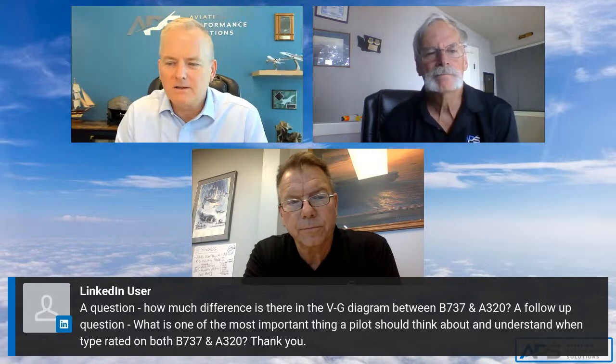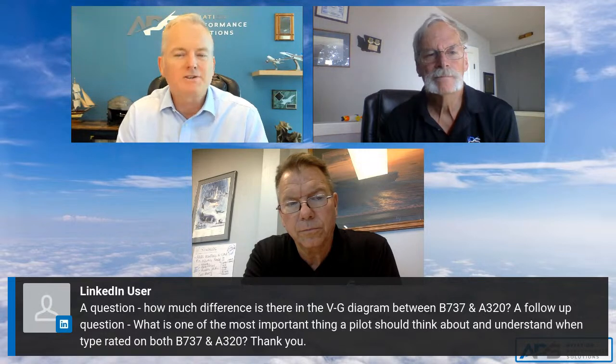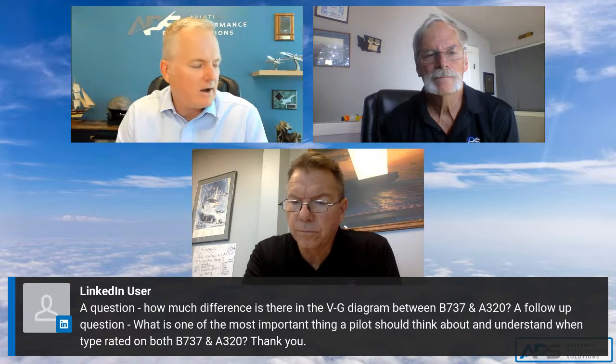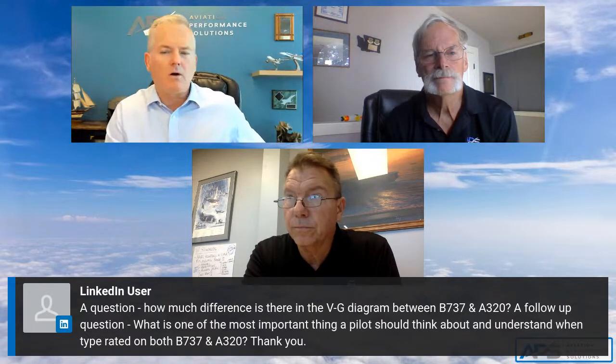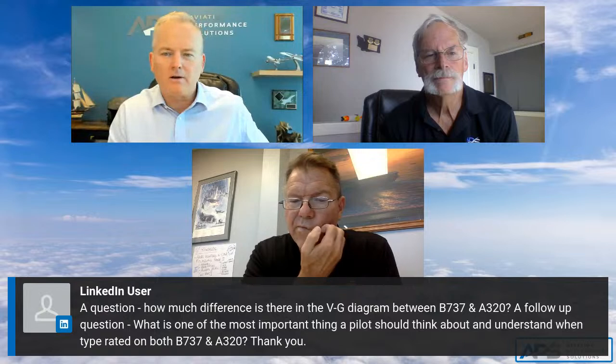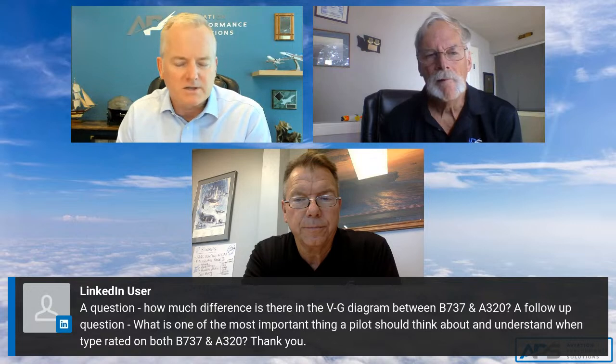Yeah, and having flown the Airbus for a number of years, the flight envelope protections that help keep you within the envelope are substantial. They're all available in normal law, but as you start degrading to alternate law in an A320, or alternate 1, alternate 2 in a 330 or a 340, they start deteriorating, and it's important for pilots to understand what goes away and what they keep. And in direct law, it's very much like flying a conventional Boeing airplane. At the end of the day, you just need to understand some protections are there, but they're not always there depending on the situation.